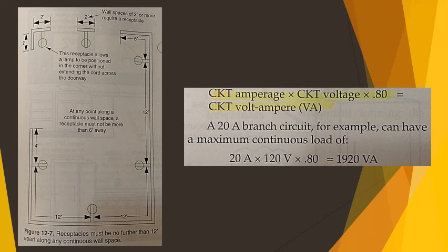This rule applies to wall spaces 2 feet or wider, including outside wall spaces occupied by sliding panels. Where fixed room dividers or freestanding counters add to the wall space, the same 6-foot rule applies. See figure 12-7 for this.